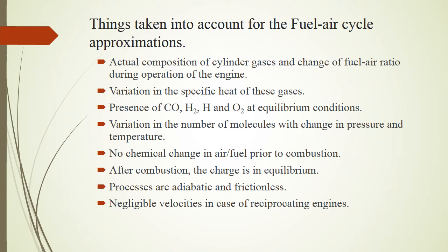The following things need to be taken care of in the fuel air cycle: the actual composition of the cylinder gases, that is fuel, air, water vapor plus residual gases, which makes up the working medium for the engine cycle. The fuel air ratio is changed during the operation of the engine, which changes the relative amounts of CO2, water vapor, etc.